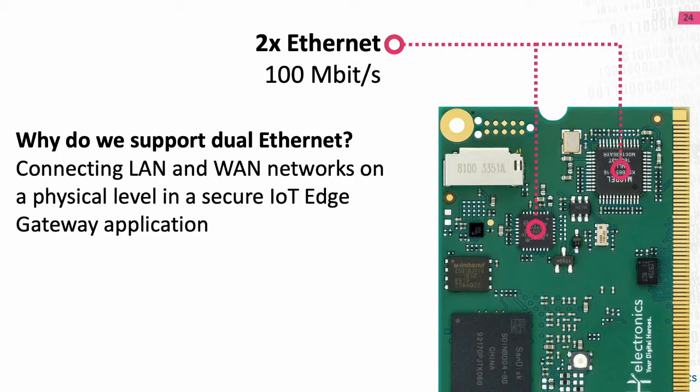But as an alternative to these 2 Ethernet ports, you can also order the DHCOM module with its RGMII interface exposed to the high-speed expansion connector. From here, all you have to do is connecting an Ethernet PHY to the expansion connector, and then you can make use of a real gigabit Ethernet interface instead. So it is really up to you if you decide to get this module with a dual Ethernet configuration, or if you prefer a gigabit Ethernet instead.